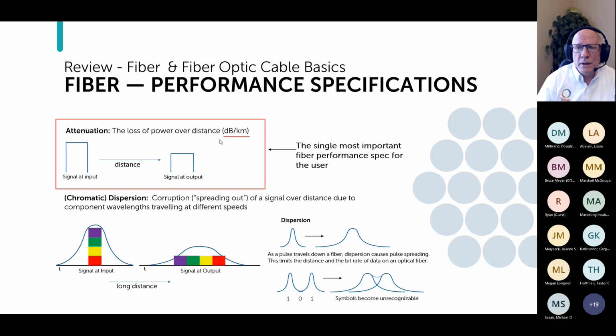So decibels is a unit of loss, and then you have a unit of length. It could be dB per mile or dB per foot or dB per furlong if you really wanted to. Here in the United States, you do sometimes see dB per 1,000 feet. That's actually really used. But the point is that it's loss over distance.